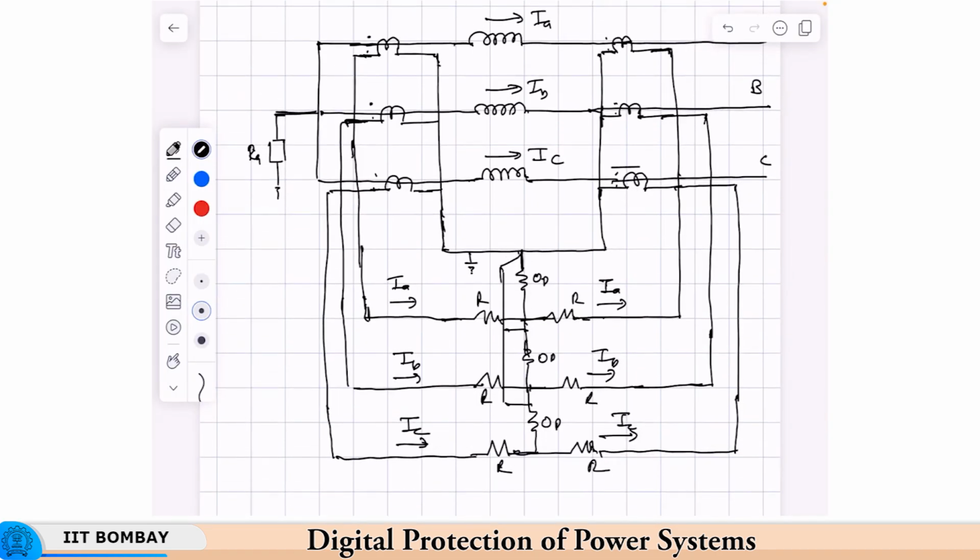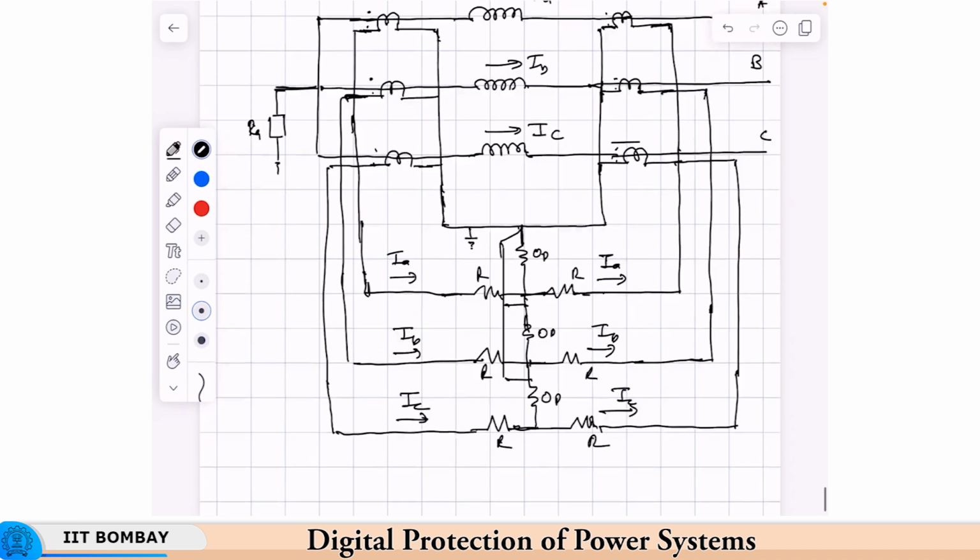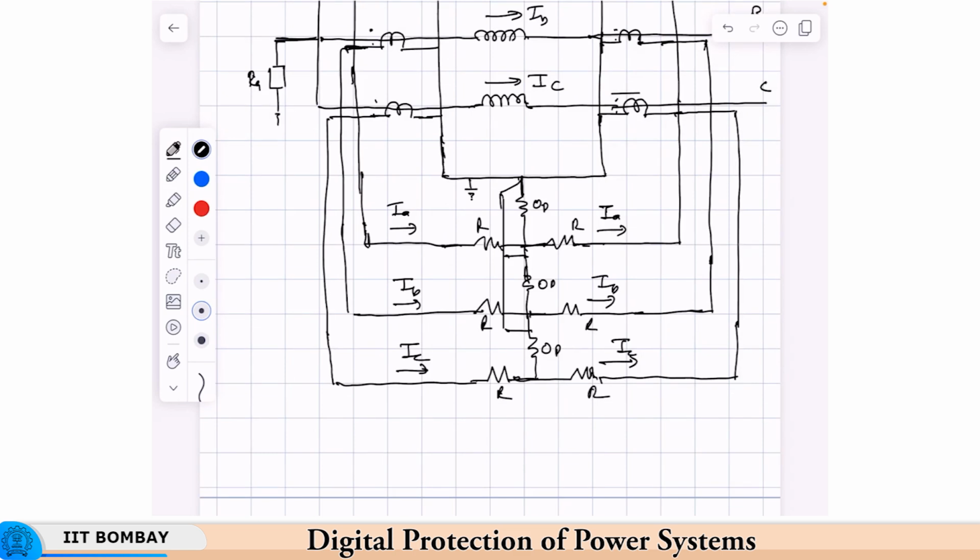Also, care has to be taken to see that these CTs are properly matched, so that you could set the percentage bias accordingly, at a lower rate.